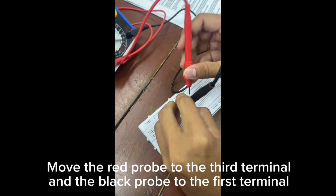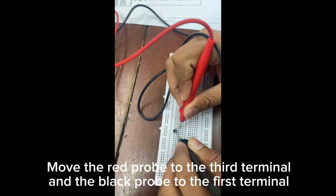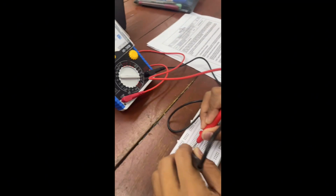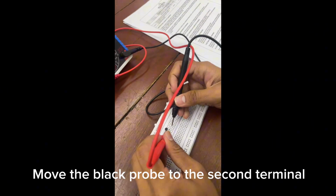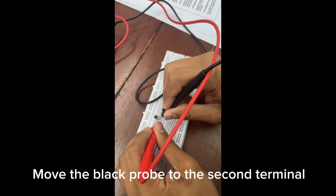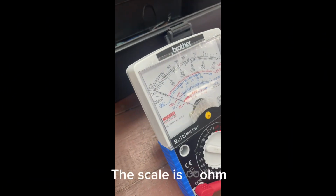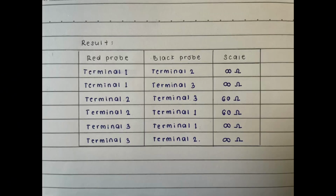And then, move the red probe to the third terminal and the black probe to the first terminal. The scale is infinity ohm. After that, move the black probe to the second terminal. The scale is infinity ohm. So, this is the result.